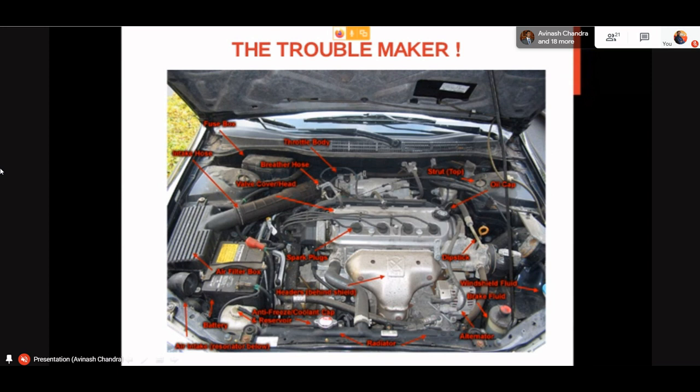Rear windscreen, why I have written it, because when we are traveling there are dust particles in the air. So this low pressure area will try to pull the dust and everything into that area when the vehicle is interacting with the flow. That's how, if you have an SUV, the rear windscreen will be dirty if you go on a ride, because it will try to pull the atmospheric or nearby particles to that zone.